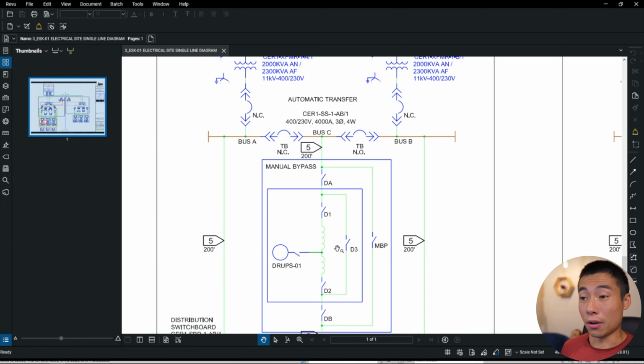Generator power is different. When you lose normal power and the generator kicks on, it takes a little bit. You have to wait 10 seconds and then your life safety kicks on, and then 10 seconds after that, something else goes on to generator. A diesel rotary UPS is a flywheel. Your flywheel's spinning, you lose power, the flywheel's still spinning, and it's providing power via a clutch and an alternator. Fascinating piece of equipment. But the building never sees that delay while the generator is starting up, because the UPS is bridging the gap for the entire building. So that's what this is.